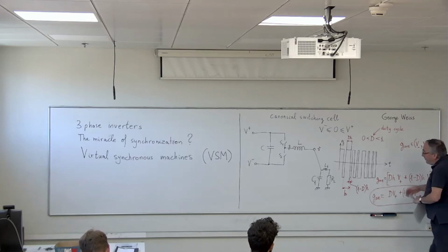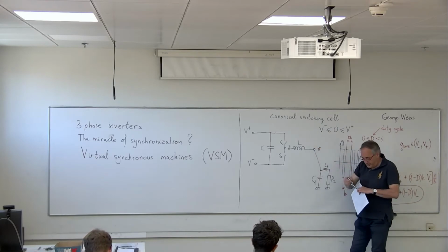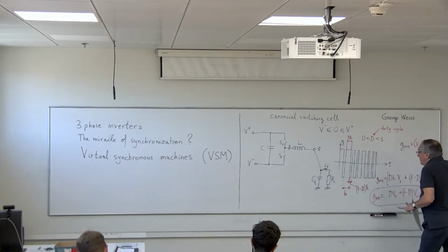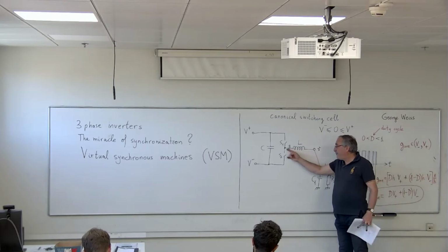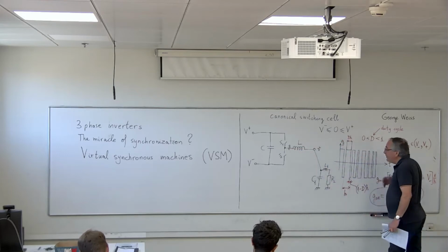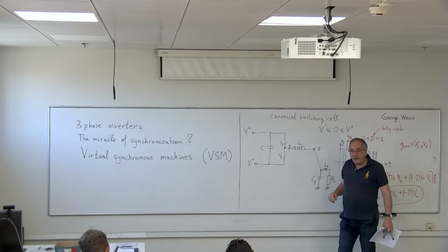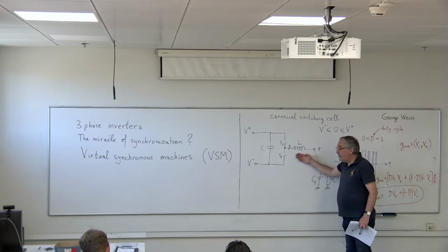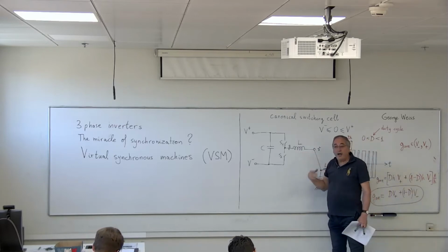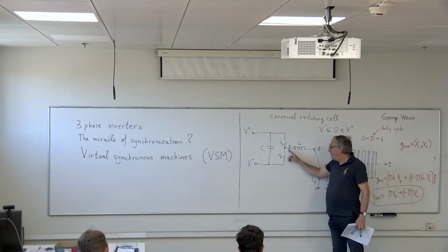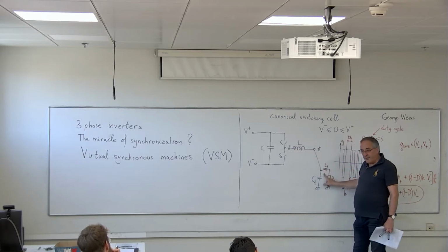Now, if there is an external circuit connected here, then this external circuit will see, of course, the high frequency present in G, but it will see it through the impedance of this inductor, which means that at the switching frequency, this inductor has a very high impedance, so that the high switching frequency will have very little influence on this external circuit.